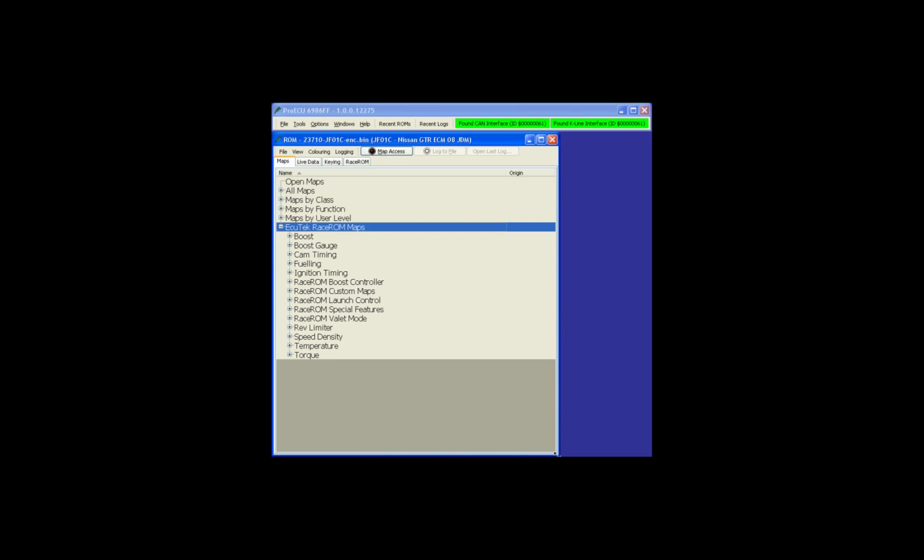It's indicated by the rev counter, like on BRZ86, so we drive the tacho to show which mode we're currently in. The map switch mode is controlled by using the cruise control, so we push and hold the cruise control button to enable map switching mode. We use the cruise control up and down toggle to change between different RaceROM modes, 1 to 4, so 1000, 2000, 3000, 4000. If we leave it, it will save after about 2 seconds. If we push the button again, it will save it instantly. So we can map switch in really 1 second.